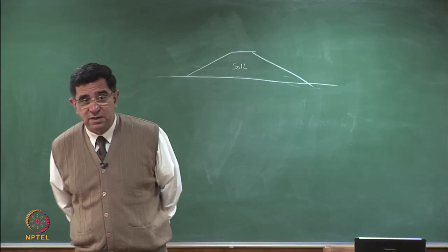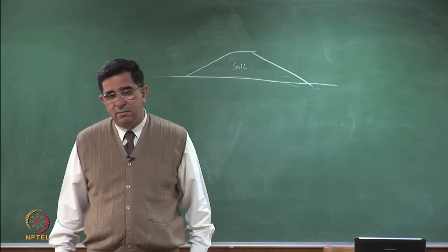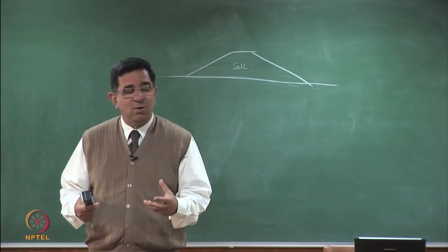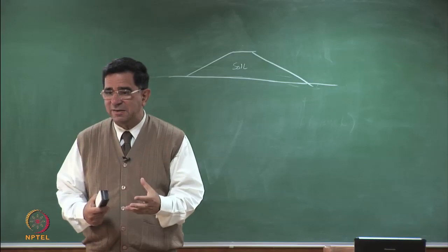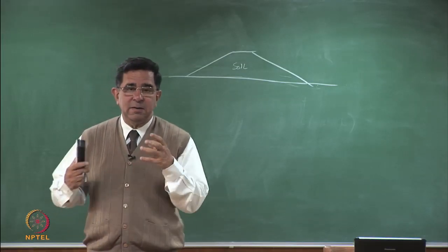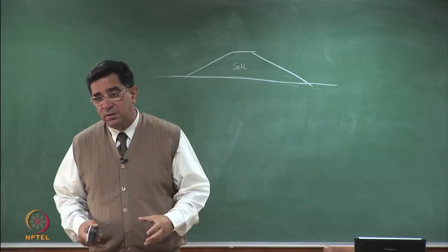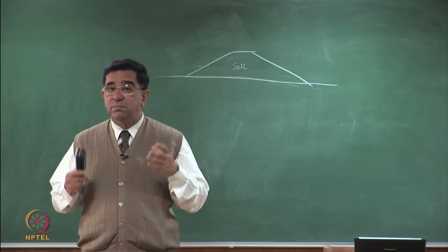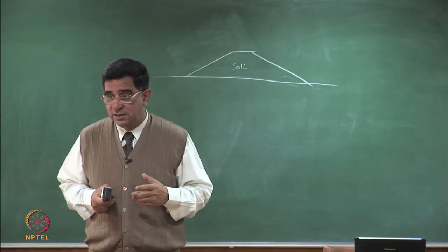Large box direct shear is a good starting point because I don't know how the sample consistency will be. Is it going to be a wet sample? Is it going to be construction and demolition waste? Immediately it may not be possible to make a cylindrical sample. So good idea. Let's do large direct shear tests.